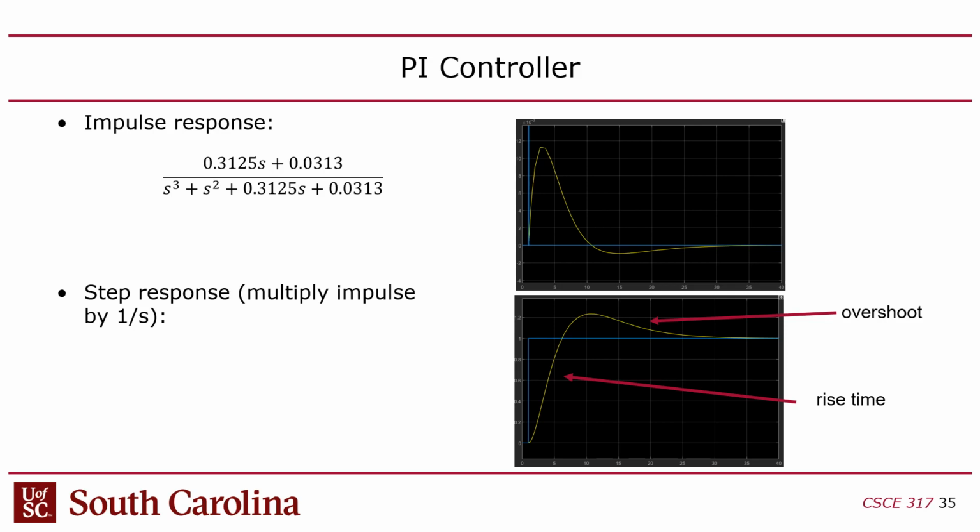So as it turns out, what I said earlier wasn't entirely true. I said the only thing I care about is that the controller and the plant together are stable. But in reality, I also care about this overshoot and rise, because I don't want the robot to have too much gusto. Plus, I want it to get the coin to the set point faster. That's the performance of the system. It has to be stable. If I pick really bad parameters, I think I could have made it unstable. I haven't tried that, and I don't know if that works out mathematically or not.